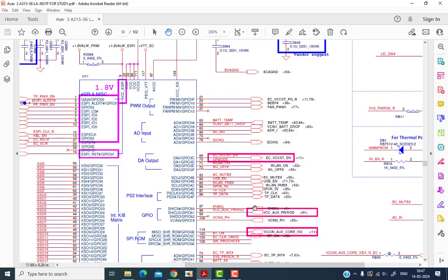And if it is a Wistron motherboard, then all these voltages are generated one after another, like the SLPS3 and SLPS4 signals are only given as enable to all the buck converters one after another, like a cascade system. They turn on one after another, they turn on each other.